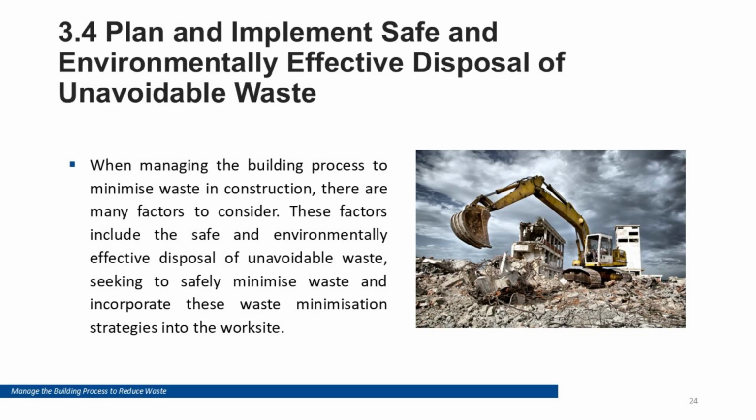Some waste is unavoidable and may be regulated or hazardous. Plan disposal by identifying the waste type, safe handling requirements, storage controls, and approved transport and disposal providers. Keep documentation such as waste dockets and receipts to demonstrate lawful disposal. Ensure procedures prevent contamination of soil and water and protect workers and the public. Safe disposal supports compliance and reduces the risk of incidents, fines, and costly remediation.